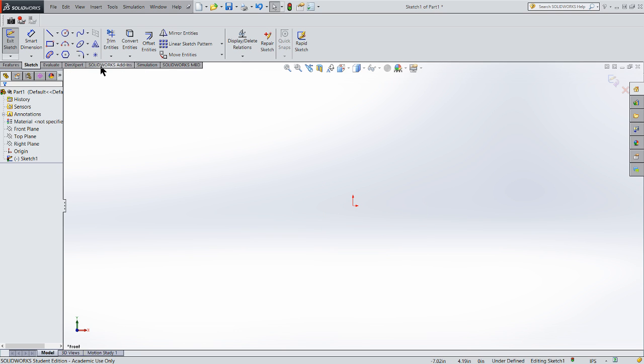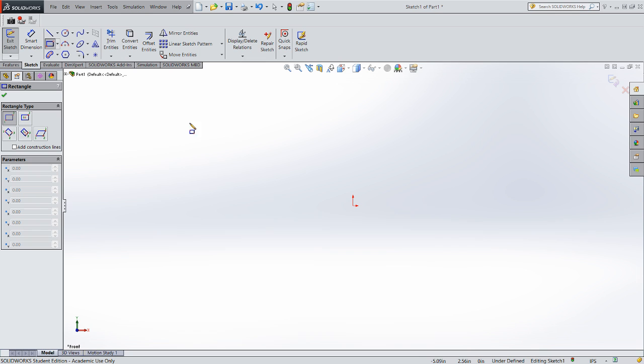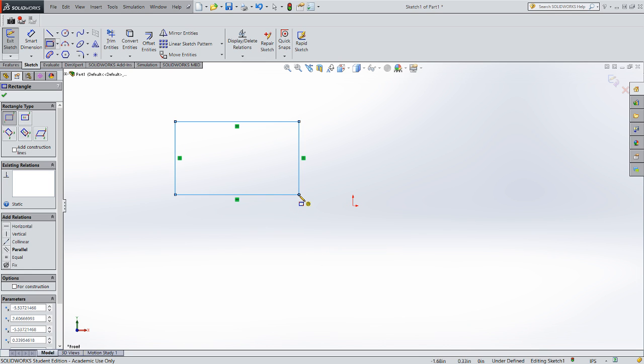So that's neat. Let's go ahead and left click, select everything, and delete it, even though we don't like to do that too much in sketching. We're going to do it for this exercise. Let me pick a corner rectangle, and I'm going to intentionally stay away from giving it a coincident spot. I'm just going to click and drag, and you'll notice that it did all of these relationships just as I mentioned. So I've got a parallel to the horizon and a vertical line on each corner.